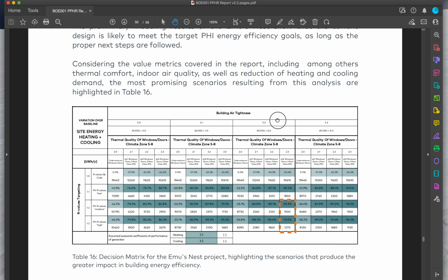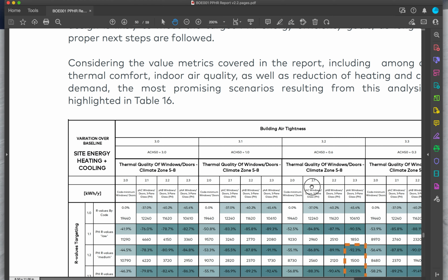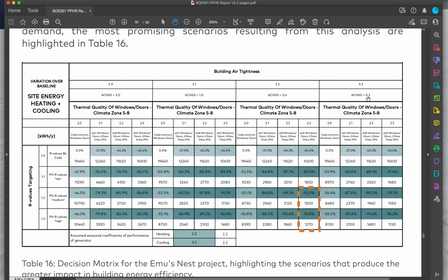We talked a lot today, so I appreciate your patience. This is the square we got to when I was looking at the passive house standard, so 0.6 ACH 50, because of certification, as well as I want to have a very tight building for durability and comfort. But I don't want to commit to 0.3 because my building is small and it's partially remodeled, so I don't want to be overly optimistic. So I want to keep the 0.6 as a design goal, and anything that I go above and beyond that is going to be gravy.